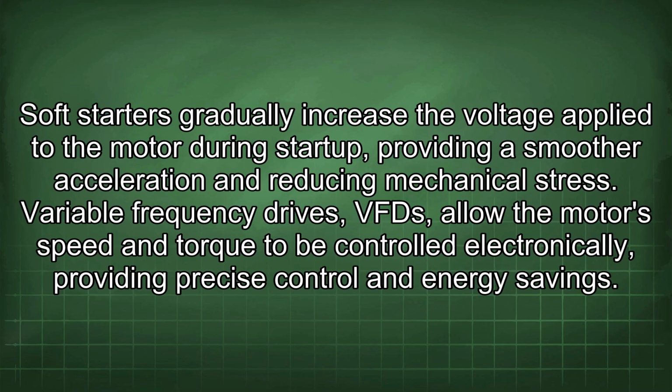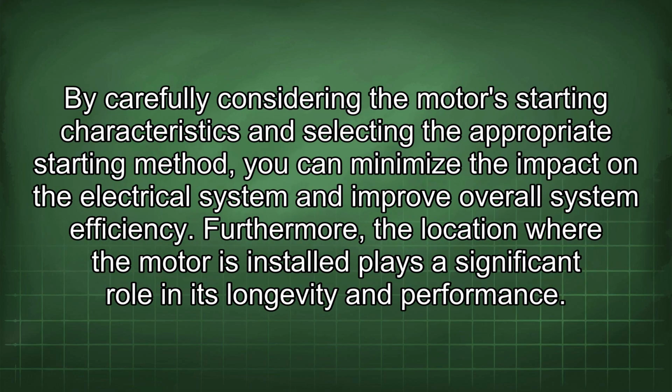Soft starters gradually increase the voltage applied to the motor during startup, providing smoother acceleration and reducing mechanical stress. Variable frequency drives, VFDs, allow the motor speed and torque to be controlled electronically, providing precise control and energy savings. By carefully considering the motor's starting characteristics and selecting the appropriate starting method, you can minimize the impact on the electrical system and improve overall system efficiency.